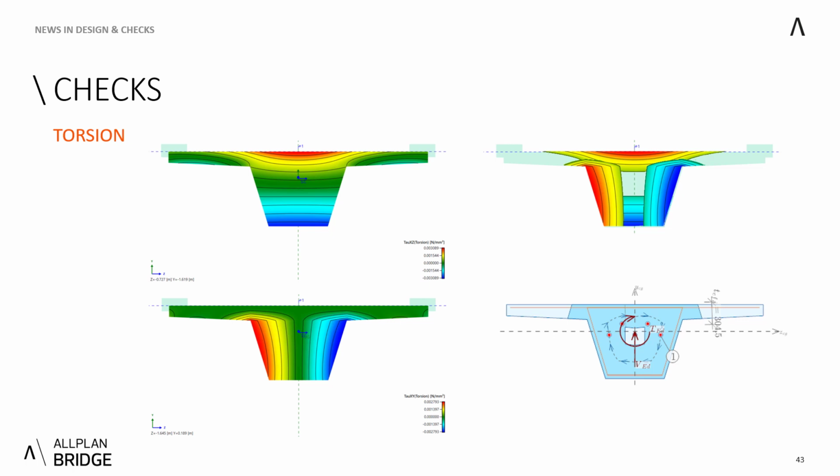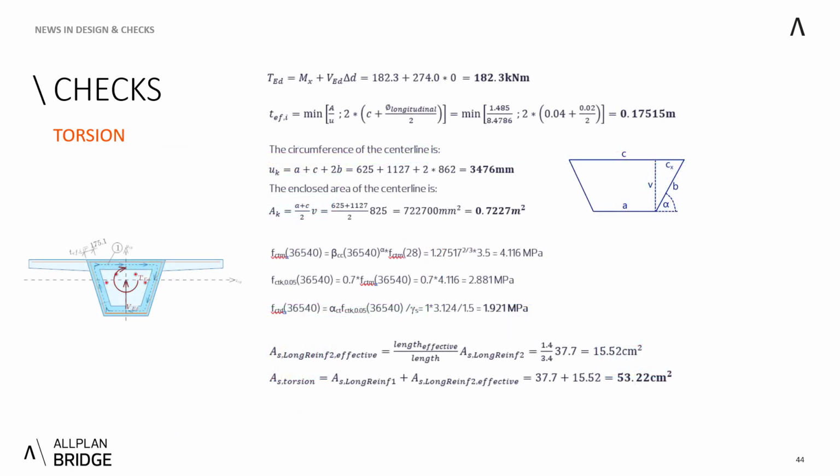By the intersection of those areas, you end up with the torsionally effective area, which you see at the bottom. And we also identify the center line of the shear flow. On the other hand, this example uses this second approach, and it's formed by the stirrup geometry.